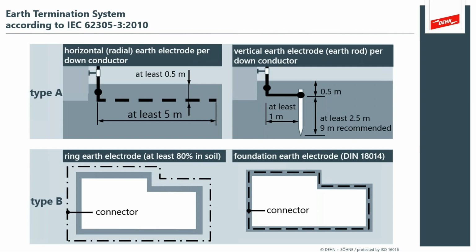And things that we see like fence post grounds, or a grid, which is actually a big grid of wire buried in the soil with electrodes vertically driven into the soil every so many, for instance 20 or 16 feet, or where it's appropriate on the site. The prevailing guidance is to get half a meter deep, below the frost line. Well, we're in Florida, so you get pretty liberal, but you still want to meet the minimum spec, so drive to half a meter.